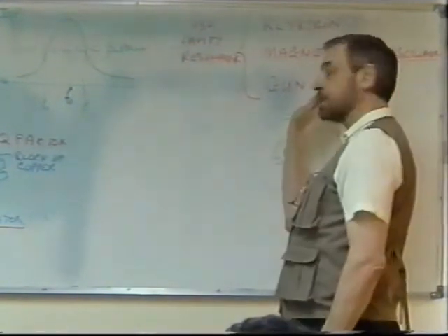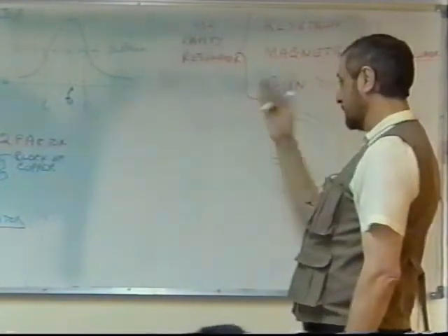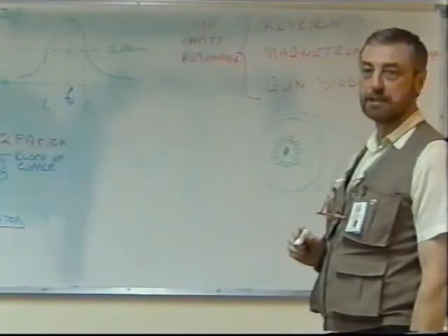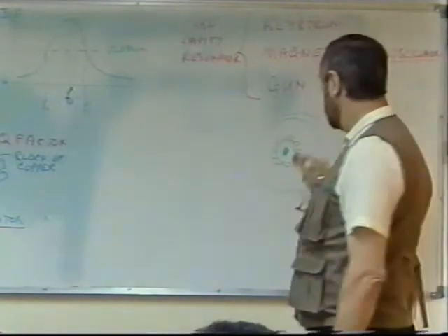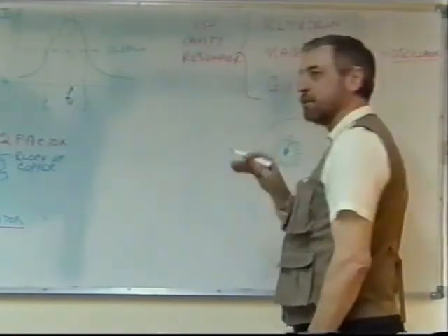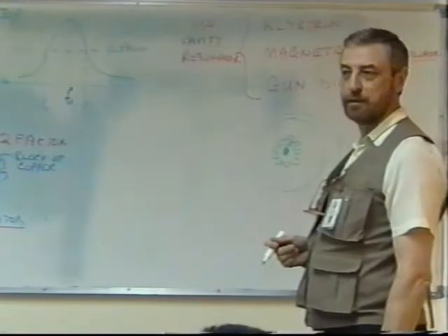So the electron beam shoots out towards these cavities. The cavities start to oscillate, and the electron beam oscillates between the two walls of the cavity. Quite complex. The electrons sort of spiral round at the frequency because of this oscillating beam.